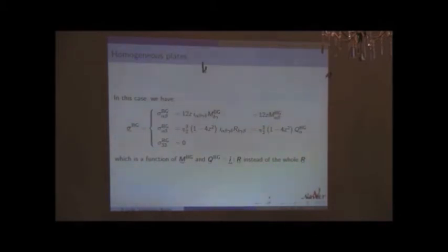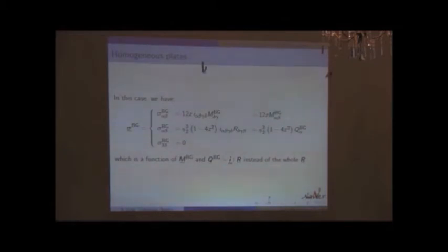And if you inject this inside the whole machinery of the bending gradient, you see that we have the transverse shear energy, which is written this way. Basically, H becomes this way because I can factor out the identity tensor. Remember, I have this identity tensor, and I will compute the energy.